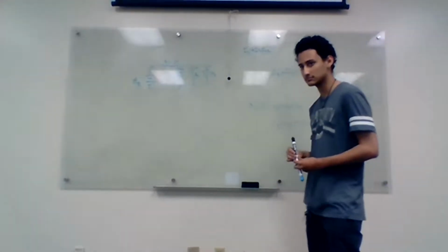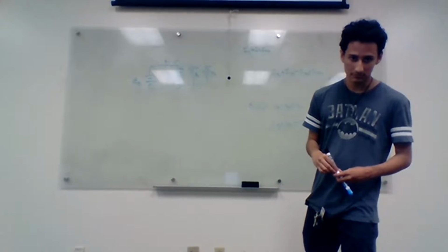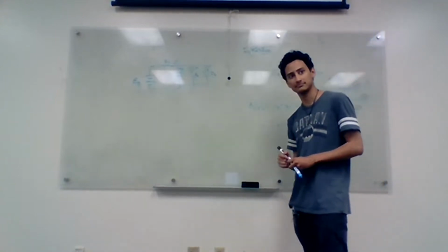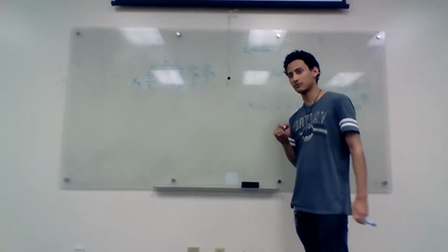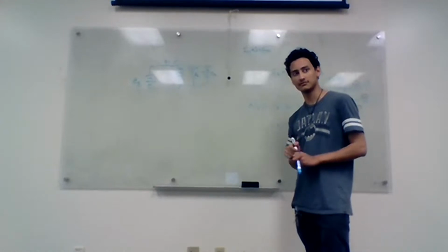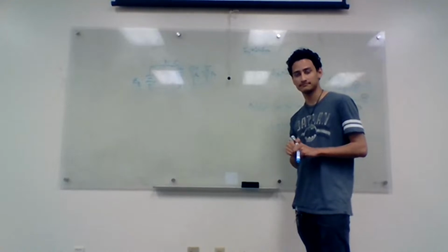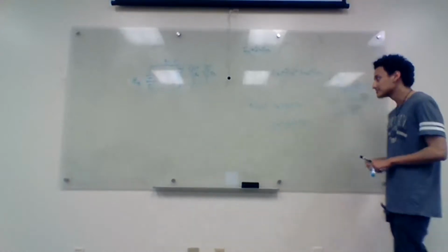So for clarification, whenever there's diode problems like that, there's not any combination that's going to need to happen, it's just KVL and KCL. Yeah, if he gave you a combination like that, don't try to combine diodes. I'm sure it works out fine, but just to be on the safe side, I would need to work out an example to make sure. If I_S is the same and everything else is the same, then yes, but what if they have different etas? Can't combine them.